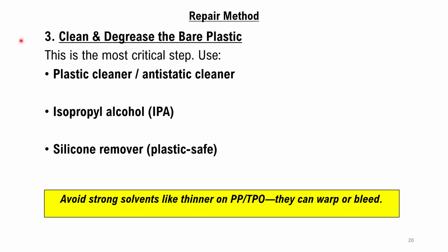Then clean and degrease the bare plastic. This is the most critical step. Use plastic cleaner, anti-static cleaner, isopropyl alcohol, that is IPA, and silicone remover that is plastic safe. Avoid strong solvents like thinner on TPO. They can warp or bleed.